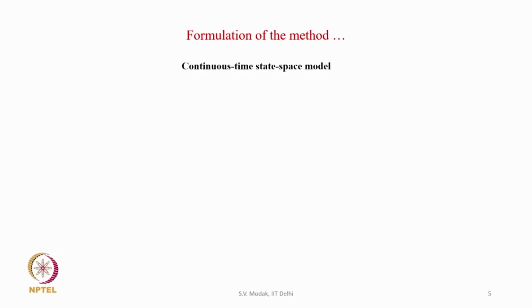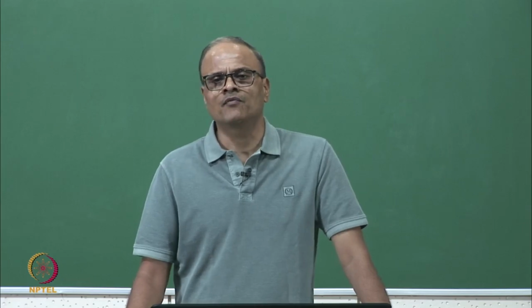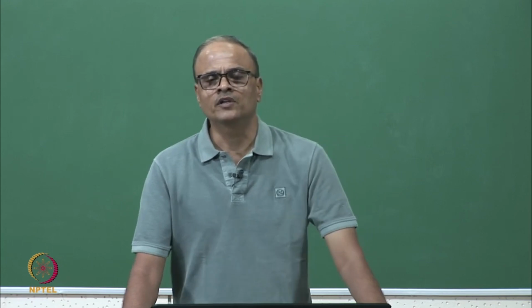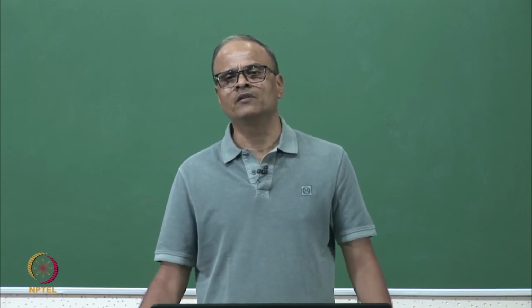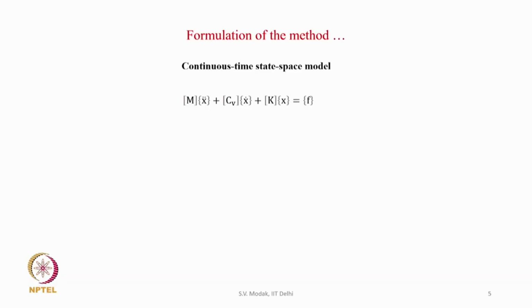So, let us first look at the continuous time state space model. Earlier we studied the state space model when we studied the eigenvalue problem for a multi-degree of freedom system with viscous damping, specifically non-proportional viscous damping. We first developed the state space model and then defined the eigenvalue problem based on it. This is the equation of motion for a multi-degree of freedom system with viscous damping.